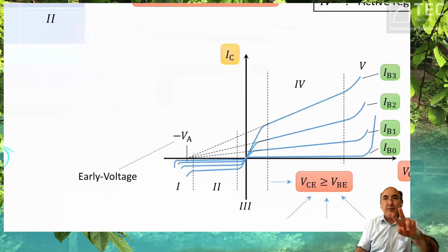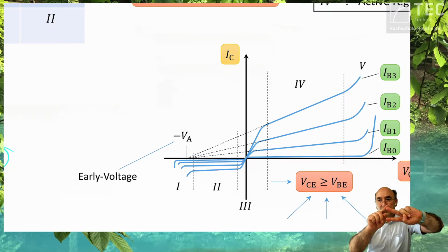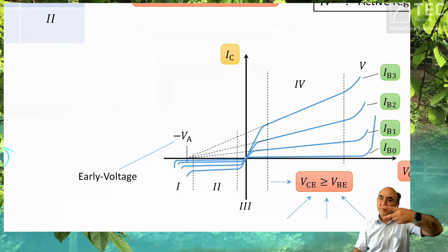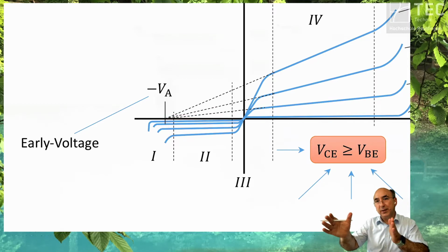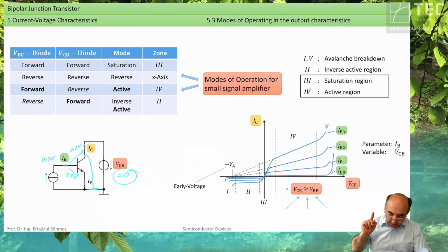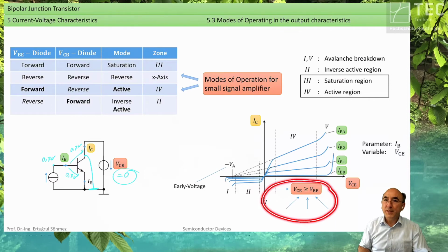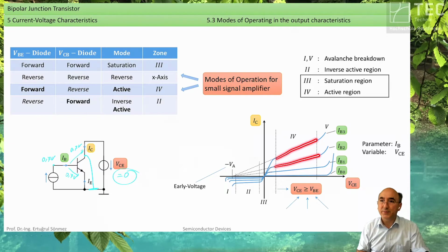And if you take the transistor and use it the wrong side down, then the previous collector is now the emitter. The previous emitter is now the collector. So if you accidentally use it upside down, then the current gain is no more good, and the breakdown voltage is no more good because all the space charge areas are now the wrong way around. Okay. It is very important to know this. If you're a circuit designer, you should keep in this area very carefully.